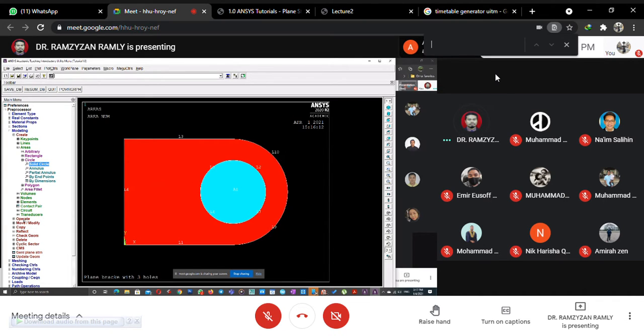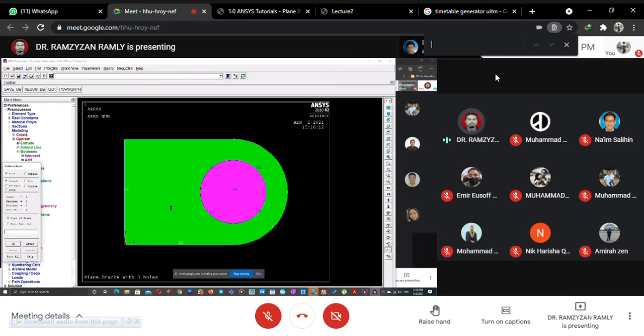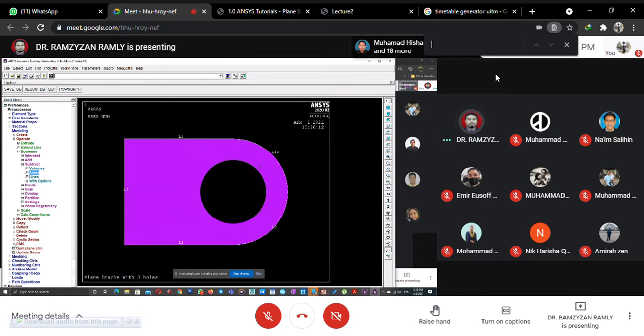Okay, select operate. Okay, booleans, and we have to subtract areas. Okay, first we want to have a bigger thing over here. All right, be okay, and then a small holes here, click OK, and now we have a hole inside here. All right,